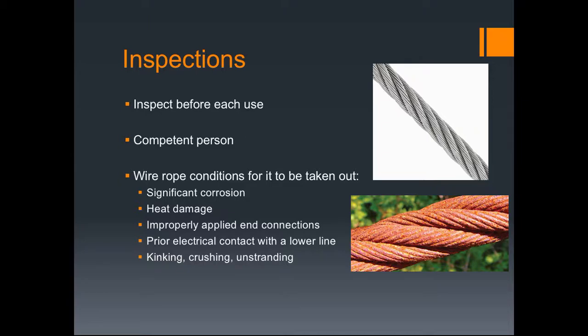And just when inspecting a crane, you should make sure that you really are doing it to the best of your ability, because once again, if you end up having an accident and then OSHA finds out that the crane wasn't fully operational and that there was something wrong with it, big fines would be coming your way. So you just need to make sure that things like tires are properly inflated and there's no deformation, cracks, or wearing of the crane itself. You just need to look for little things like that as well as the big things.